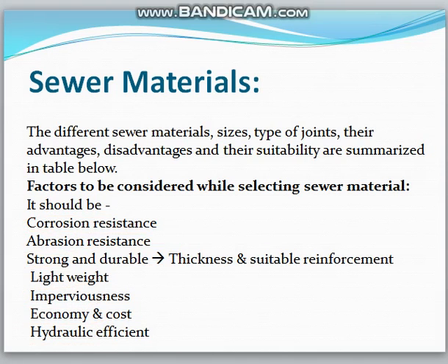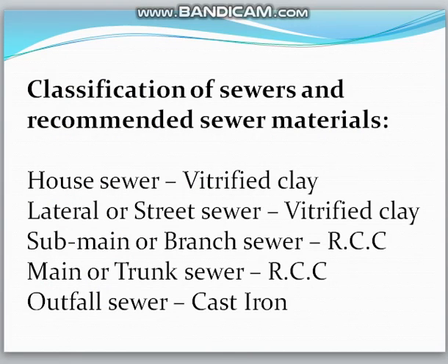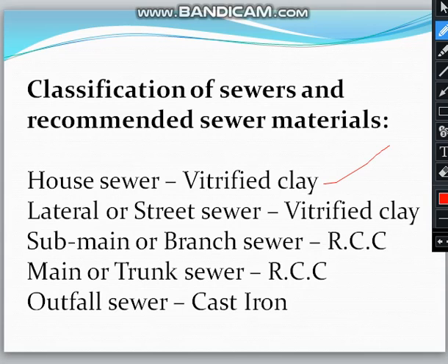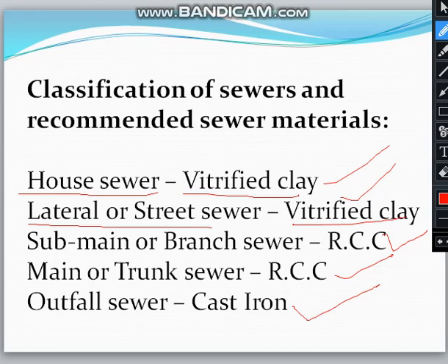Next, classification of sewers and recommended sewer materials. For house sewer, vitrified clay is mostly preferred. For lateral or street sewer, also vitrified clay. For submain or branch sewer, RCC is used. For main or trunk sewer, RCC is used. For outfall sewer, it is cast iron.